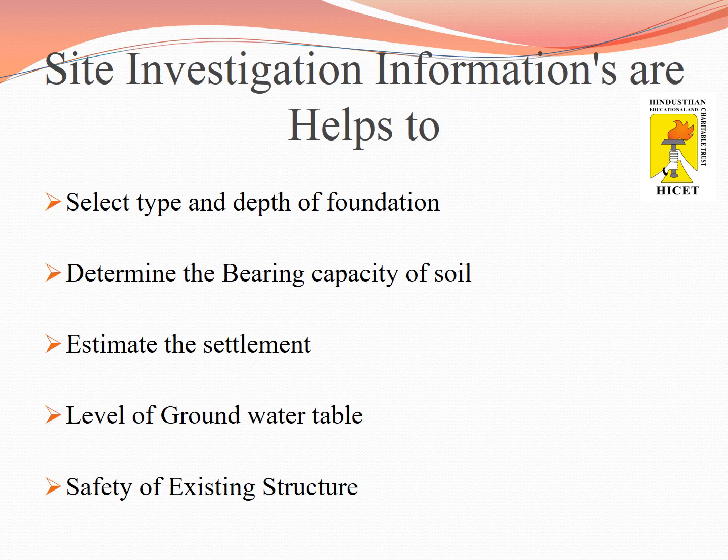By the site investigation information, we can select the type of foundation and depth of foundation. Also, we can determine the bearing capacity of the particular soil which is directly available below the ground surface, and also we can estimate the settlement of the particular soil which is available in the site.